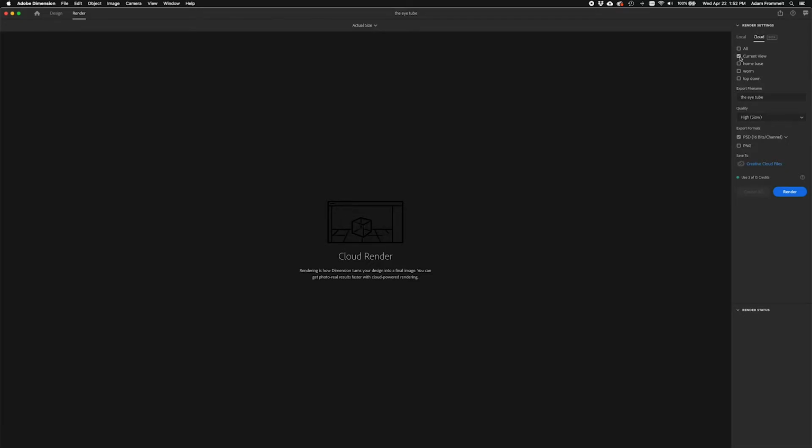What I have selected right now, just the current view and just as a Photoshop file, is going to require 3 credits, and that's based on time on their server. Pay attention to that. The cloud renders, again, they do go super fast, but I would save those for when you have really, really heavy duty, a lot of packages, when you're rendering out the full suite so that you can see the entire suite together. That's when I would suggest it's worth using some of those credits and rendering on the cloud. Locally, it's going to be about 10 minutes per view per file.